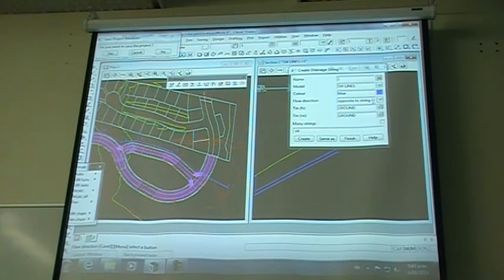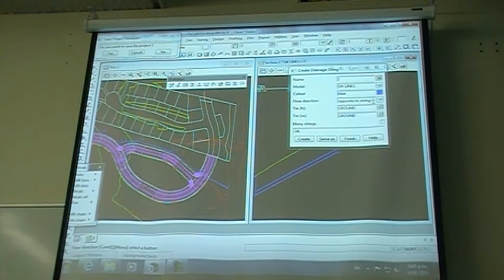When you plot this out under the long section plot, your changes are going to start here. Okay, all the grade information starts at this point. The problem being that, of course, the drain layer is going to build it from the other end. So he's got scope for mistakes to be made because he's constantly trying to interpolate backwards.